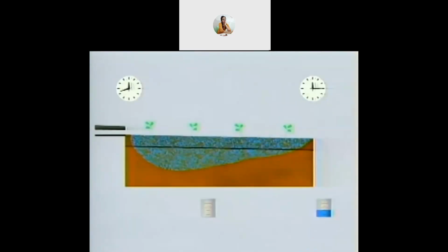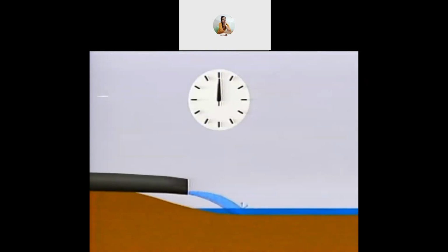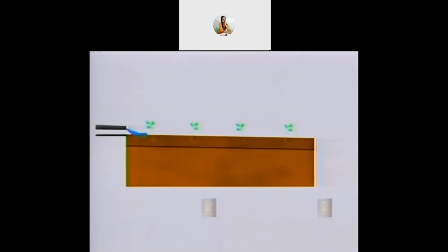Number 1 is subsurface irrigation. Its advantages are: A. This method is suitable for forage crops, pastures, small grains, and flowers. B. Soils like sandy soils having low water holding capacity, high infiltration rate, good permeability are economically irrigated with high water use efficiency. C. This method requires almost 20 to 40% of water as compared to surface method.